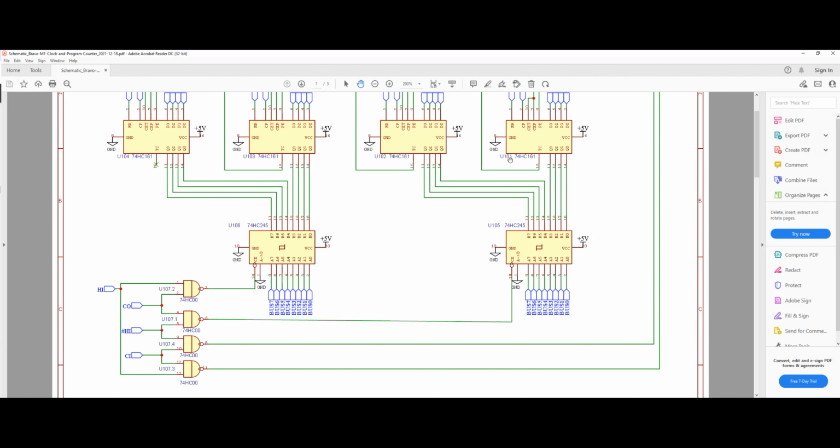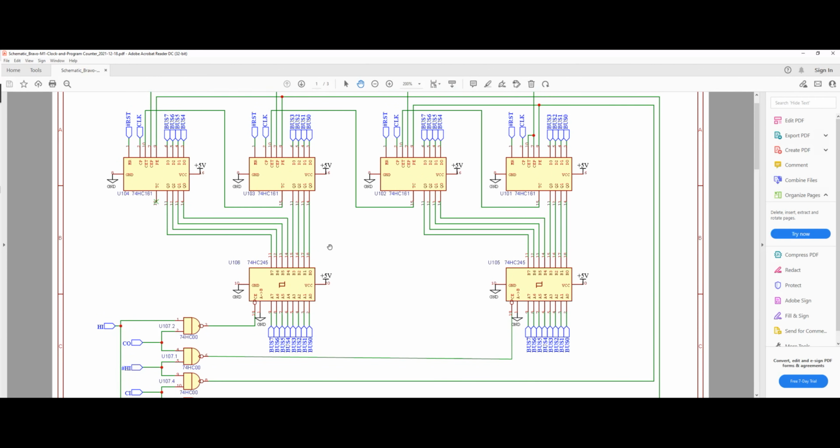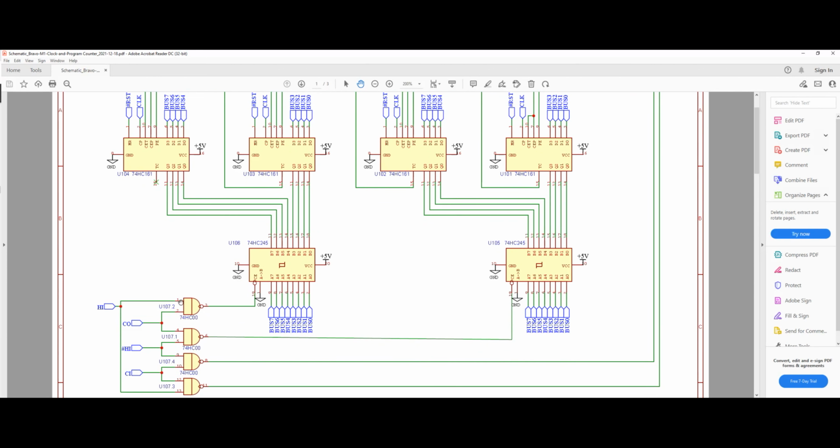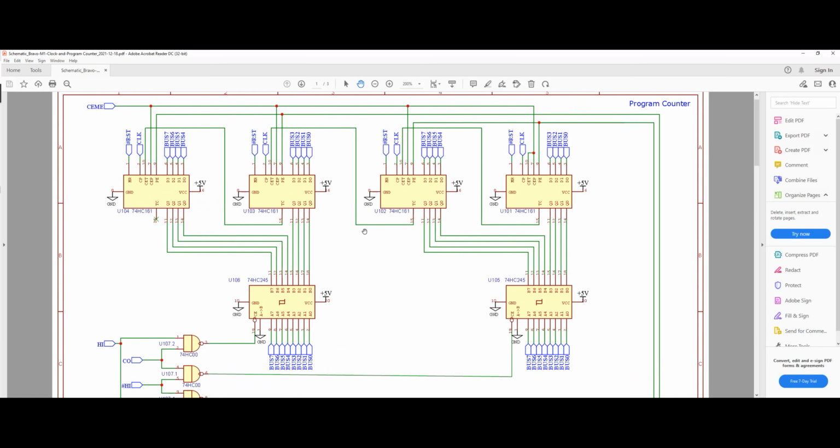Now, once that operation is completed, the only thing that we need to do is just bring the HI signal high. When we bring the HI signal high, the inverted HI will be low. Therefore, this side of the circuit will be disabled from an output perspective. And then the high byte side will be active because the HI will be high, the counter out will be high, and therefore the output of this NAND gate will be low, and therefore we have an output on the high byte side.